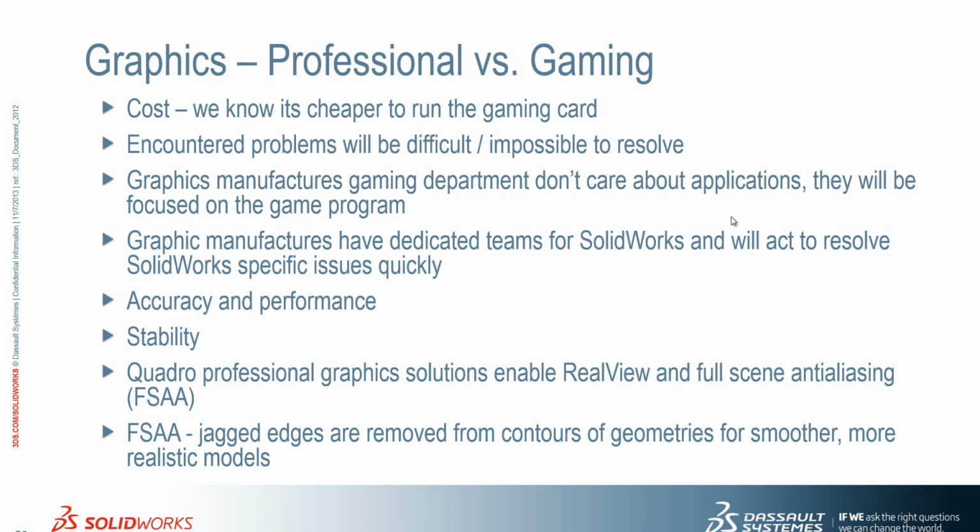If it's an NVIDIA Quadro card, they have a dedicated team that fixes graphical bugs against that service pack or whatever SolidWorks version you're in. Whereas with a GeForce card, there's no one. The people that work for GeForce are only interested in things like what frames per second you can get out of games, and whether there are any bugs with games. They're not interested in SolidWorks. So always try and run a Quadro card if you can.